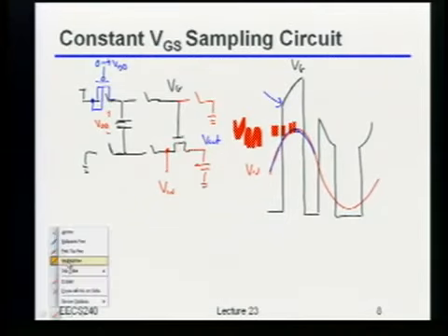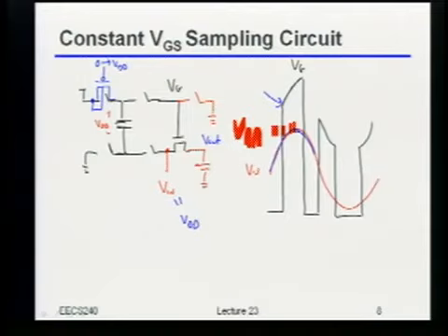Okay, so let's say that Vin happened to be VDD. What should VG be when Vin is at VDD? 2 VDD. Yeah, it better be 2 VDD. Now, this switch, of course, is on, so how about that PMOS transistor right there? It's going to be forward biased towards the body. Not only do I actually have a diode that's turned on, which of course is just this one, but in fact, the transistor itself is actually going to be on also, right? Because remember, for PMOS, whatever the higher voltage is, that's the source. So I've got 2 VDD over here, I've got VDD at the gate. Guess what? That PMOS is nicely on. In other words, it ain't going to work. And not only that, you turned on a diode and you may have blown something up and you're generally unhappy.